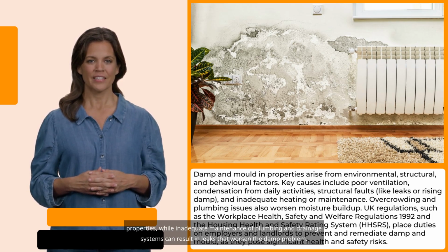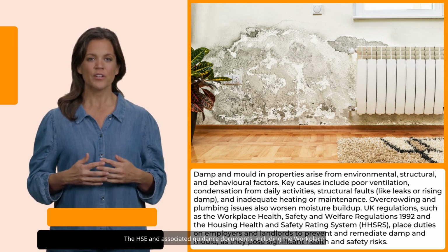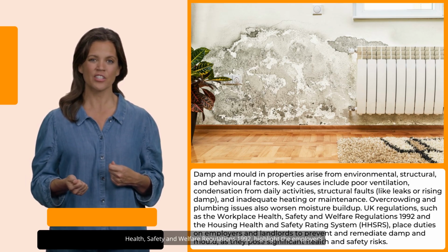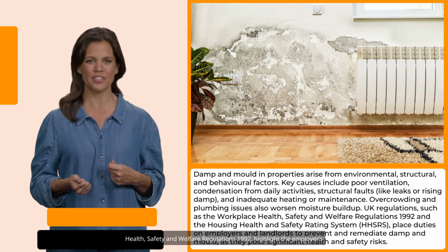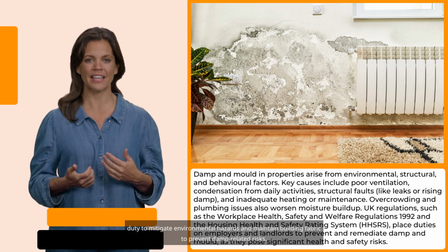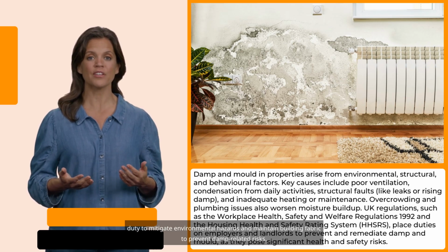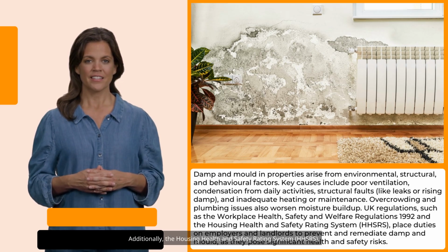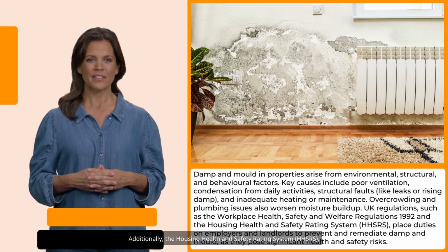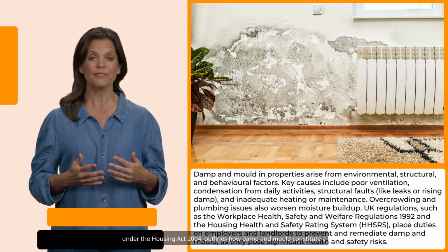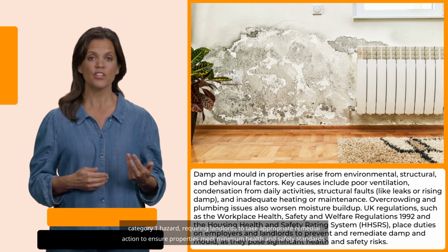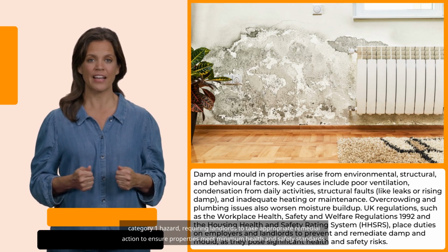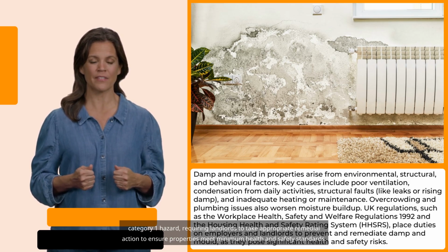The HSE and associated guidance documents, including the Workplace Health, Safety and Welfare Regulations 1992, highlight the employer's duty to mitigate environmental hazards and maintain building fabric to prevent damp-related risks. Additionally, the Housing Health and Safety Rating System, HHSRS, under the Housing Act 2004, outlines how damp and mould constitute a Category 1 hazard, requiring landlords to take appropriate remedial action to ensure properties meet minimum health and safety standards.